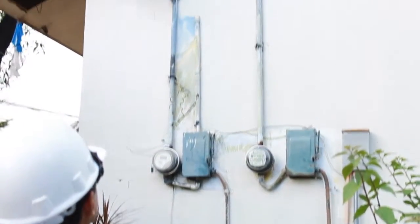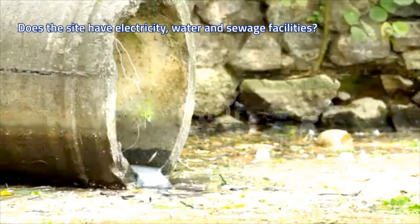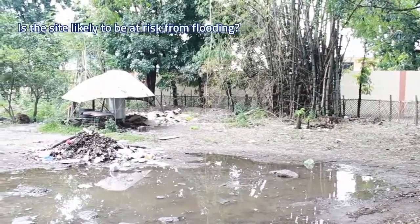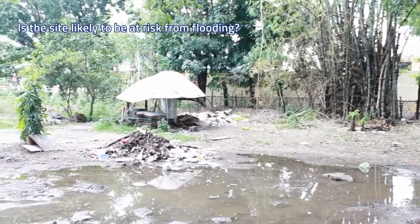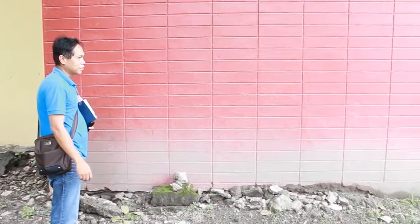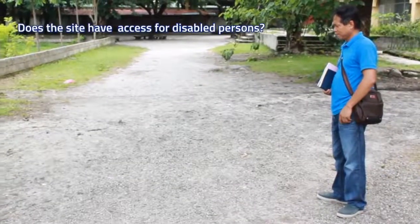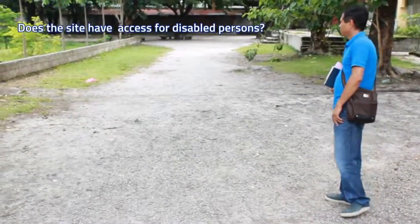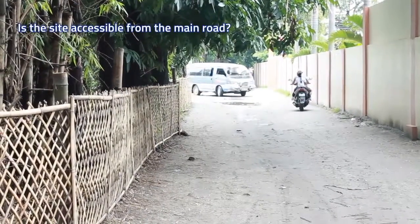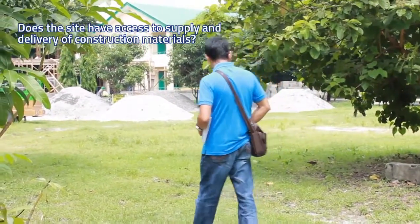These are: does the site have electricity, water, and sewage facilities? Is the site likely to be at risk from flooding? And if so, what remedial works are needed to mitigate the risk? Increasing elevation to address the effect of inadequate drainage systems. Does the site have access for disabled persons from the roadside to the school entrance? Is the site accessible from the main road? Does the site have access to supply and delivery of construction materials?